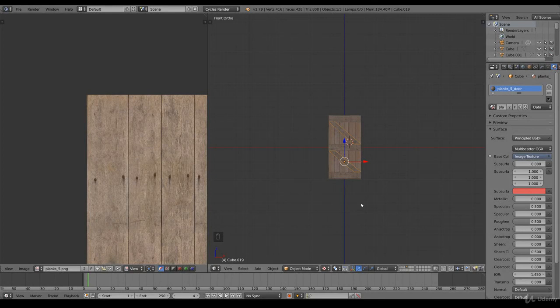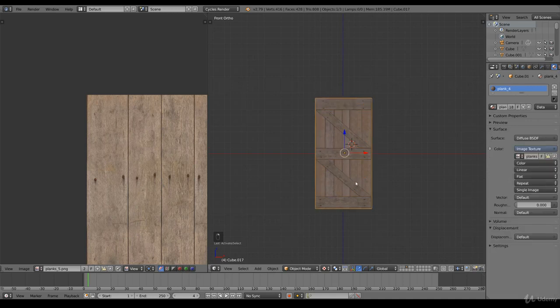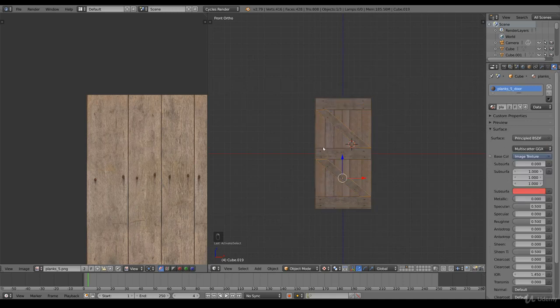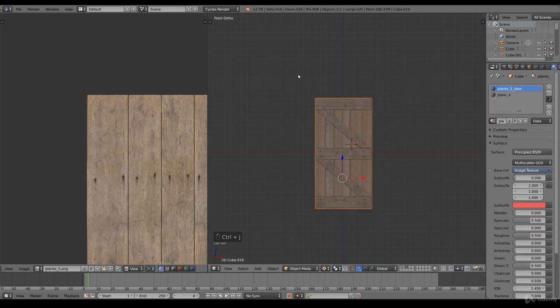So we created the door and I want to put this in our medieval building. We need to apply two more steps to do that, because right now there are three separated objects and we want to make one object out of it. So press B, left mouse button, and select all the objects, and now Ctrl J, and now it's one object.